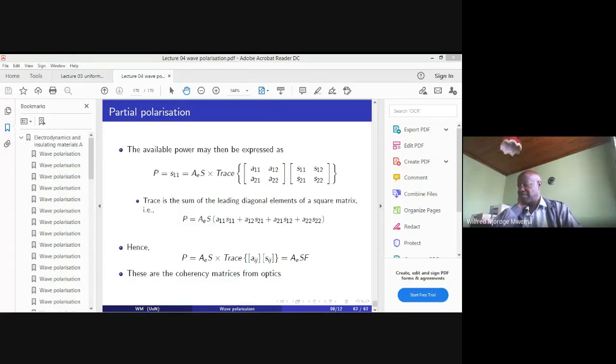And the curl of H is equal to J, which is the conduction current, plus the displacement current density. If the medium is lossy and the fields are harmonic time dependent, then we can write it as sigma plus j omega epsilon. The j omega epsilon deals with the displacement current, because j omega is just d/dt, and epsilon E is just D.